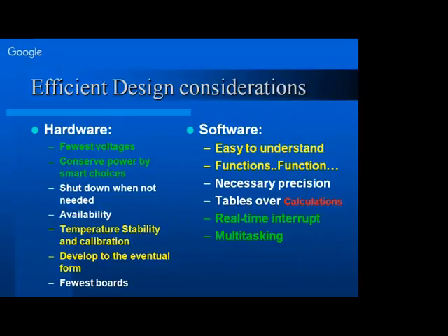And real-time interrupt. So there is vector polling, and there are two methods for when you develop any kind of real-time systems. There is vector polling, and there is the scanning technique. So in the scanning technique, your CPU continuously keeps on scanning the event. Okay, whereas the interrupt driven, the vector driven method is very efficient, because they are inbuilt, and those interrupts have a particular vector location or addressing. So that is the real-time interrupt consideration.